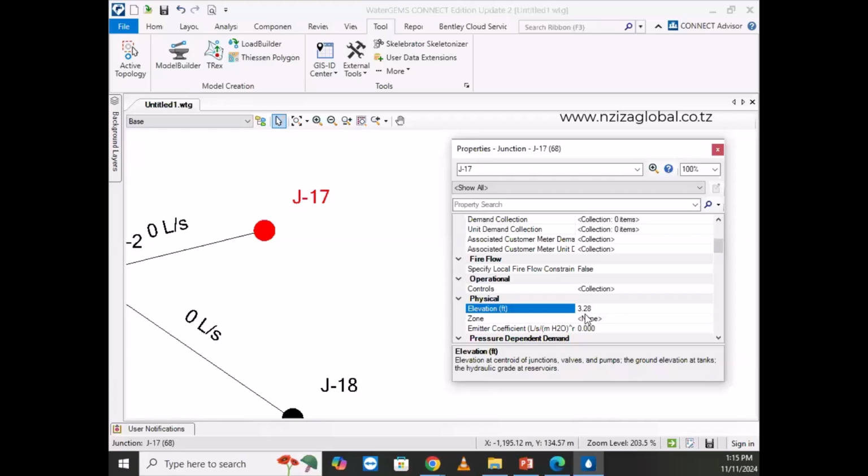You say that you used to use EPANET. In EPANET, for example, when you say 10 meters, and it was set in meters and the unit changed to feet, it continues to equal 10. It will be 10 feet.